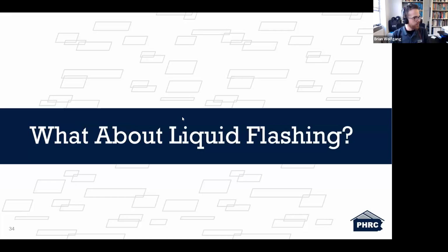So before we take a brief pause, I just did want to talk for a moment about liquid flashing. Now, I'm not going to go in depth about this. I'm not going to mention specific manufacturers, but there are some folks who will see liquid flashing as an alternative to some of the common acrylics, butyls, rubberized asphalts. What I see most commonly as situations that would push someone to consider liquid flashing is really complex details where a tape is difficult to install. But there are some considerations here.